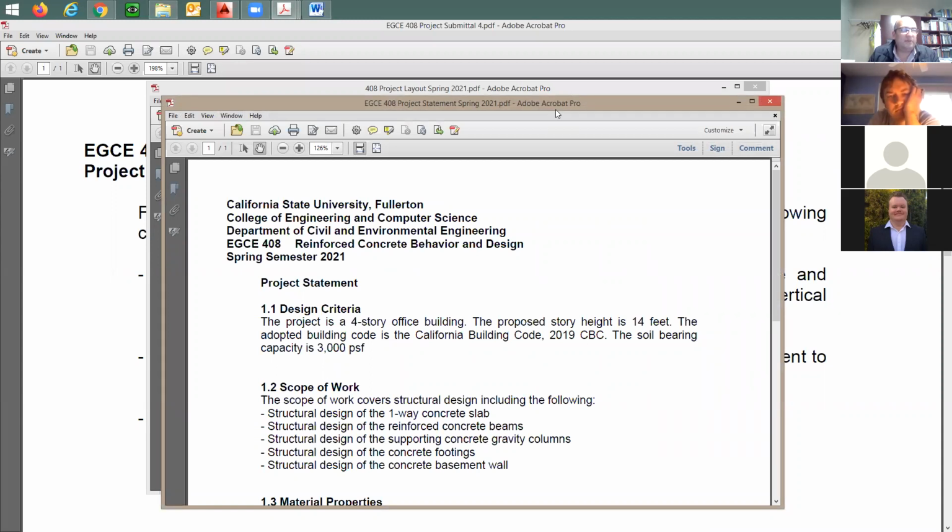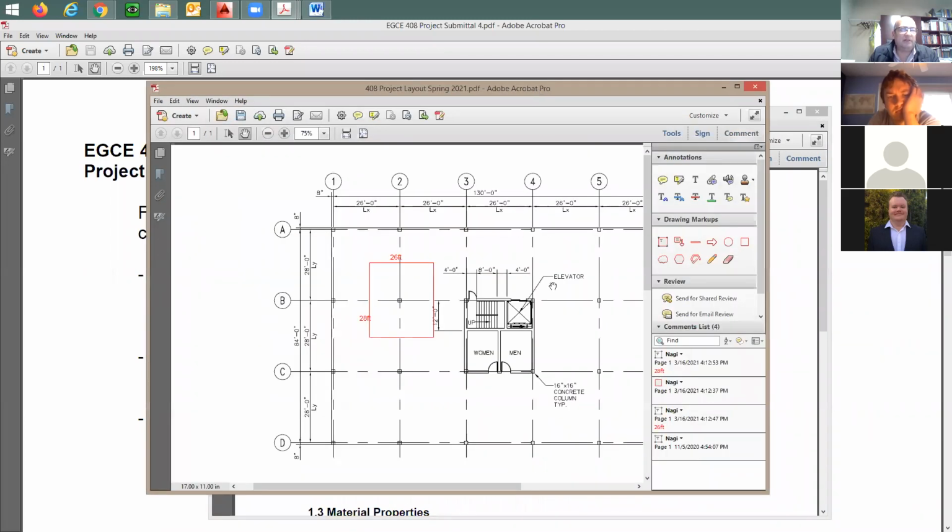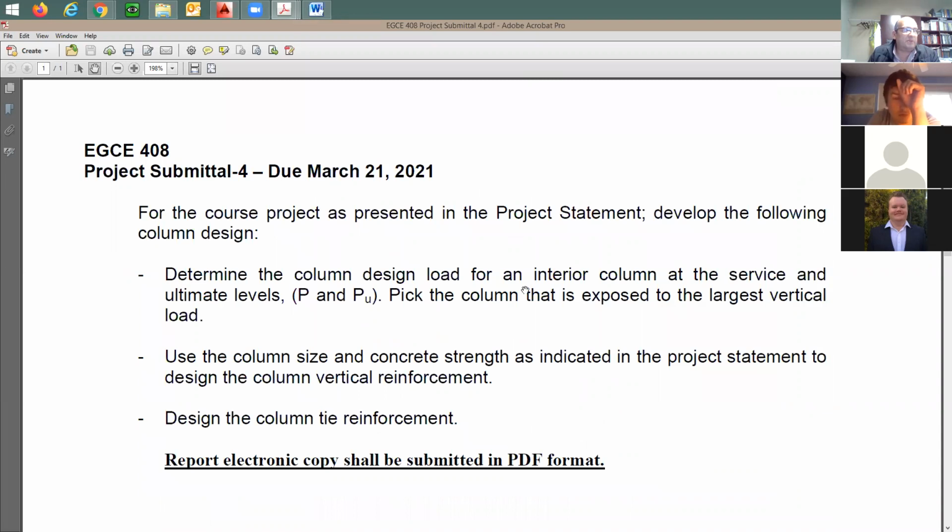So you need to figure out the total load. How do you do this? You do dead load for the roof and live load for the roof. Dead load for the third and then for the second. And then you add them up. At the end, you're going to have this P ultimate on the column. How do you do it? At the end of the day, you need to have 1.4 dead versus 1.2 dead plus 1.6 live load. And then at this point, you say this is going to be the design load for the column. And this is going to be under this piece here.